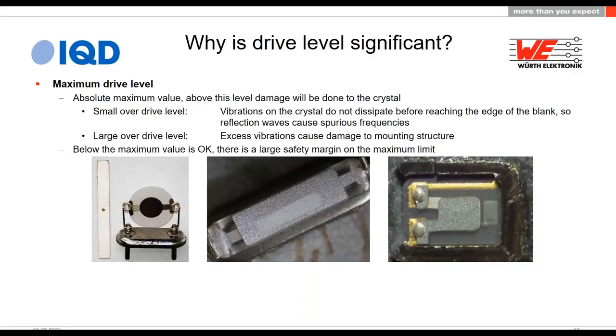However, you don't need to be too worried about this. You just need to get the drive level below the maximum that's on the data sheet. If you look at crystal data sheets from any of us that do crystals, you'll notice that the drive level is a uniform value that we stick on all of our crystals. We don't change it depending on the frequency or the specification or anything like that. So that tells you there's a pretty broad safety margin, even in our own work. So don't be too panicky about being 5 microwatts just over the drive level and thinking, oh, I need to get that down. Honestly, I would probably say that's going to be fine.